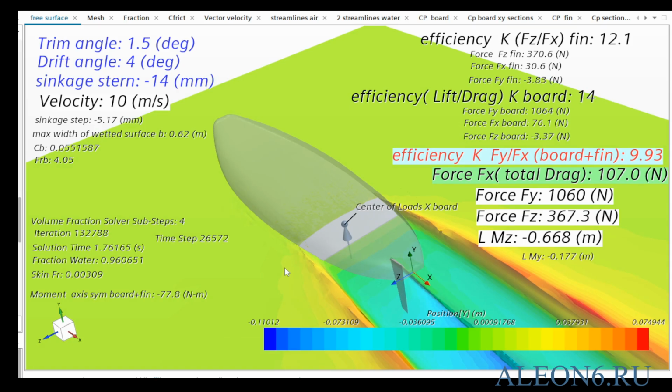This suggests that under near-ideal, flat water conditions, this modified system requires less thrust, the forward component of sail force. This could be advantageous in light winds, potentially allowing the board to remain on a plane for longer periods. Questions regarding stability and performance in choppy water were beyond the scope of the simulation and will be addressed during practical on-water testing, to be covered in Part 3.